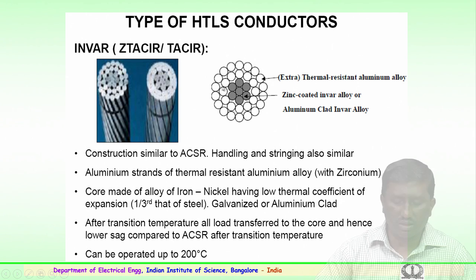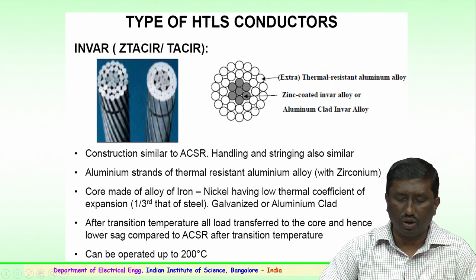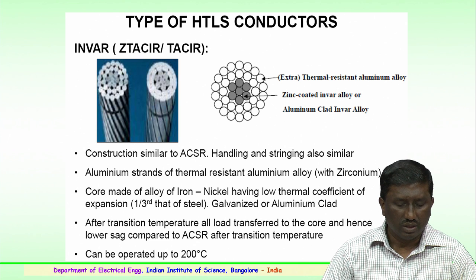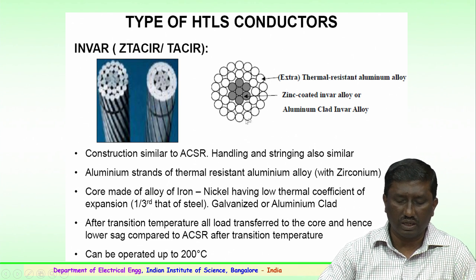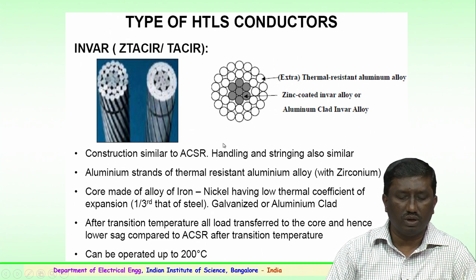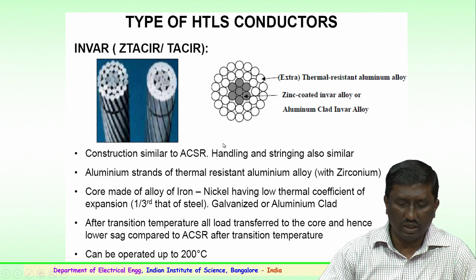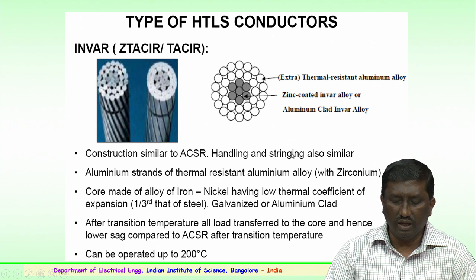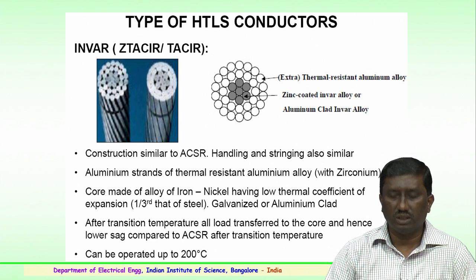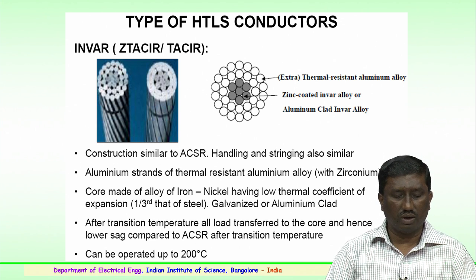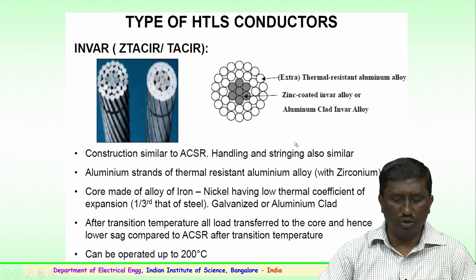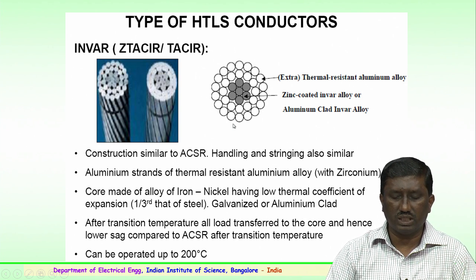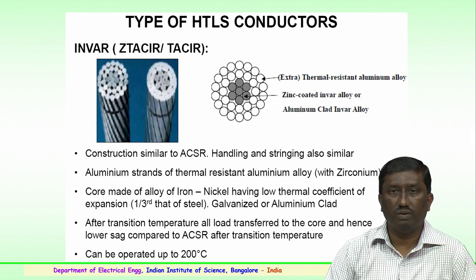Inside is a zinc coated invar alloy or aluminum clad invar alloy. The construction of this conductor is similar to aluminum conductor steel reinforced conductor, and handling and stringing are also similar in the tower.